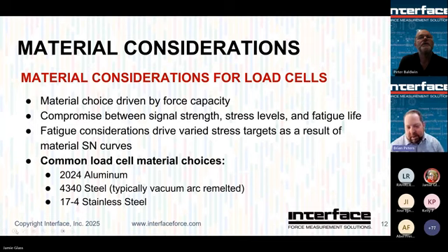Engineers target the beam thickness. Beams are where we apply the strain gauges to ensure the bridge is going to give the desired output. Some of our load cells are 4 millivolt per volt, for example, as standard output. Most of our fatigue cells are at a lower level than that, around 2 millivolt per volt. Still, that's often what many of our competitors offer as a standard output. So everything's relative, but everything is a compromise.